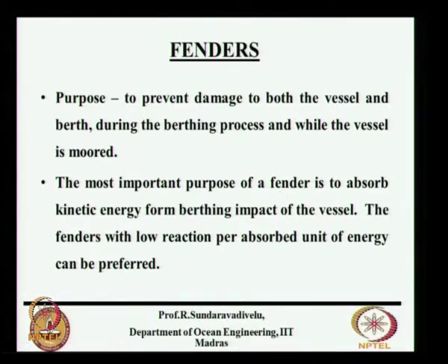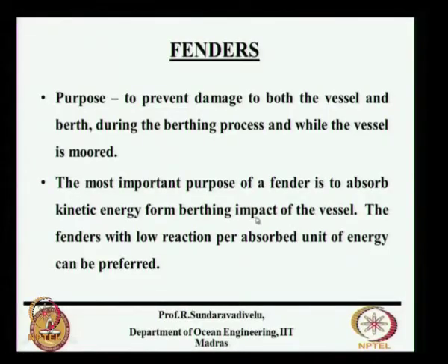Normally we talk about life of the structure. Marine structure life is about 40 years, whereas typically the fender life is only 10 years. It does not last more than 10 years, mainly because of the impact that is imparted on the fender, and a lot of deflection takes place. That is why the fender's life is only 10 years. The fender with a lower reaction per absorbed unit of energy can be preferred. So, the kinetic energy is transformed. The force to be calculated should be very less for unit energy, that is the purpose of this.